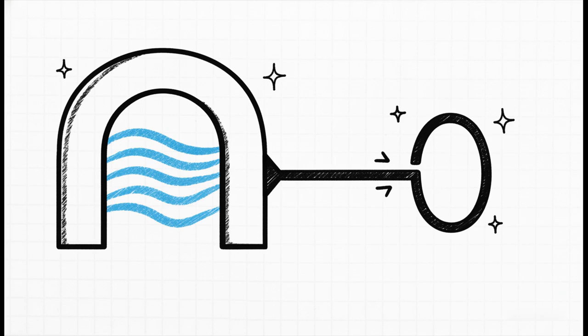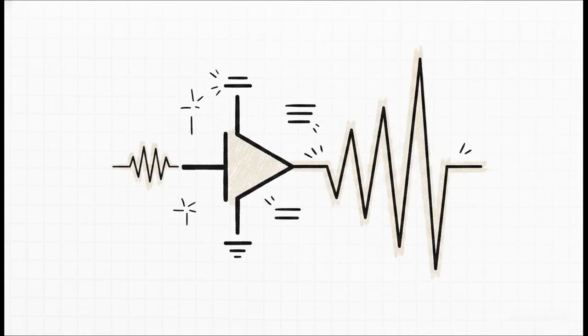To find Y11, the equation says V2 has to equal 0. In the real world, unlike Z, where the port was open, V2 equaling 0 means the output port is hard short-circuited to ground. So you're probably wondering, why do we even need both?